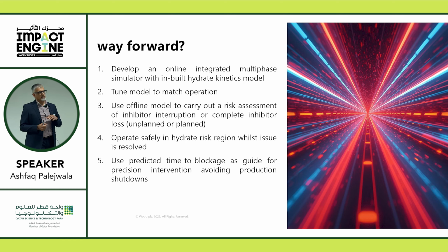Now, typically, I know some operators will say, if I'm at the risk of hydrate formation, I will shut down. I will not take the risk. So if I lose a pump and my analysis says I'm in the danger area, I will shut down, fix the pump, and restart. Now, of course, if you shut down and restart even a single pump, it might take you 6 hours, 8 hours, 10 hours, 12 hours to get back online. So then you're losing production.